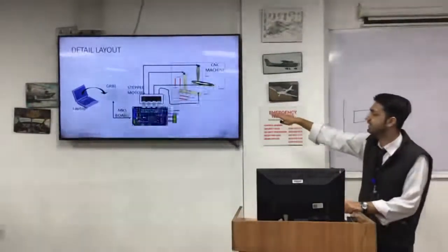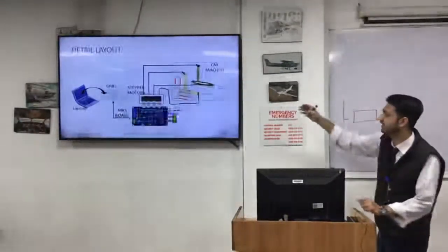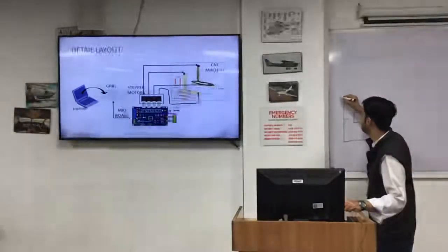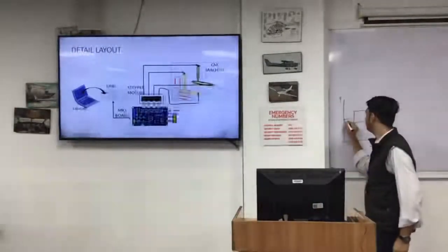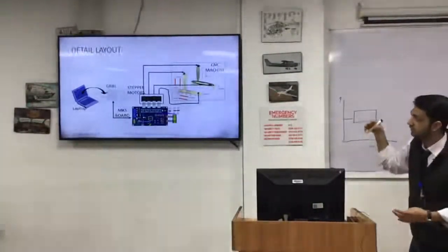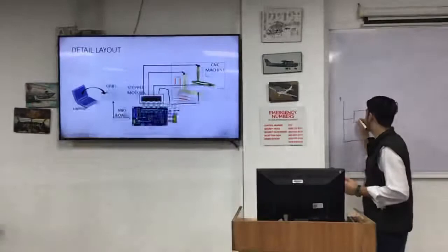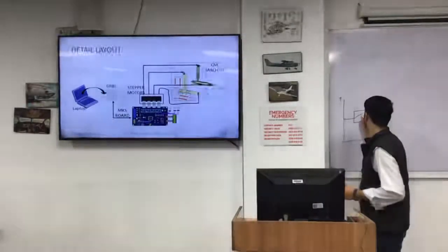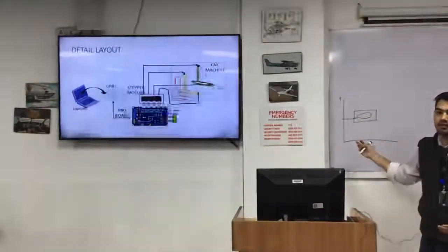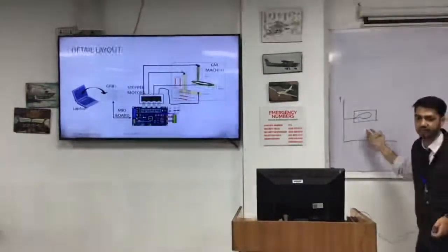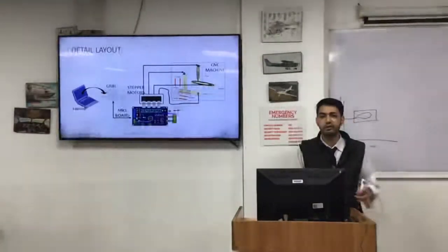The motors at the x-axis will move, the wire will move in this direction, and if the motors at the y-axis will move, the wire will move in the upward direction. So the motors at the x-axis move and the wire moves in the forward direction, and the motors at the y-axis will move in conjunction with the motors at x-axis, so the wire can move in a shape like this. And this will create an aerofoil shape. It is directly related with aeronautical engineering and our project is a part of control engineering design.